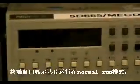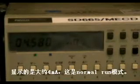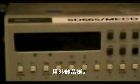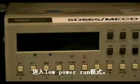And if we take a look over the digital multimeter, we can see that the part is burning about 4.5 milliamps, and this is in normal run mode. So the first thing we're going to do is take the part into a low power run mode where we really just start to run off the crystal that's outside the part and take it as low as we can go, using a loose regulation inside the part to get as low power as possible.